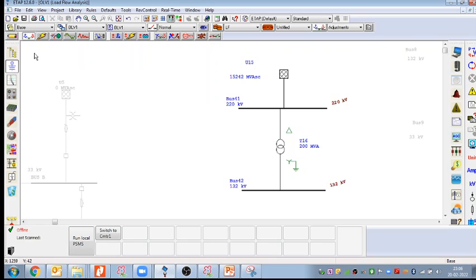Oh, okay. What about fault current? How much fault current is coming? 7.1 kilo ampere. That is very less, negligible right now. And how much have I selected? That is 40 kilo ampere. So why such a huge difference? Why a huge difference? Because what will happen?